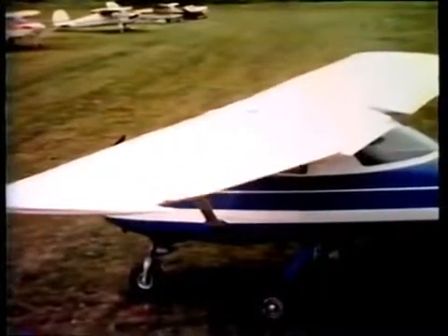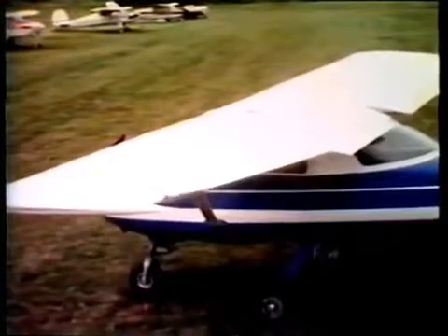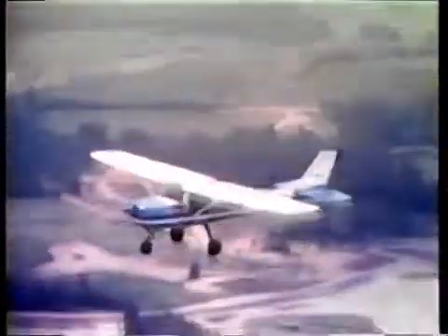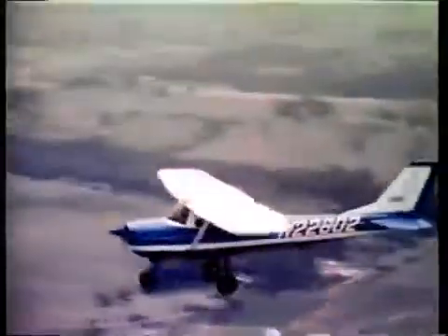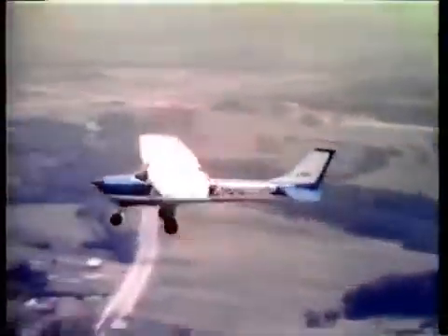Ailerons, too, are movable surfaces. They are placed outboard toward the wingtips. As they are moved, they vary the airfoil, increasing the lifting force on one wing while decreasing the lifting force on the other. In some aircraft, there are other devices to vary the aerodynamics of the wing. Most of these are high lift devices, such as flaps, which reduce the stall speed during landing and takeoff.